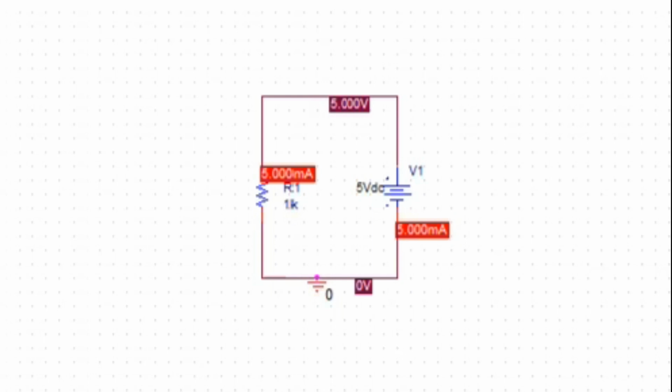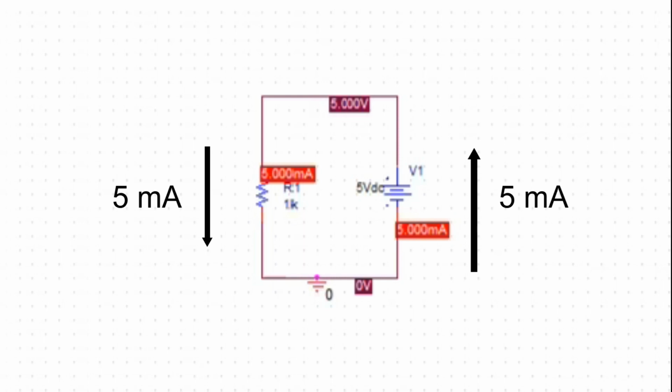For example, to find a voltage across the resistor on the left, with this given polarity, plus on top, minus at the bottom, the voltage difference is 5 volts on the plus side, minus 0 volts on the negative side, resulting in 5 volts. In terms of the current, PSpice follows its own convention such that the current is always flowing positively through the element starting from the current marker. I have attached arrows indicating how the current flows given the location of the current marker.